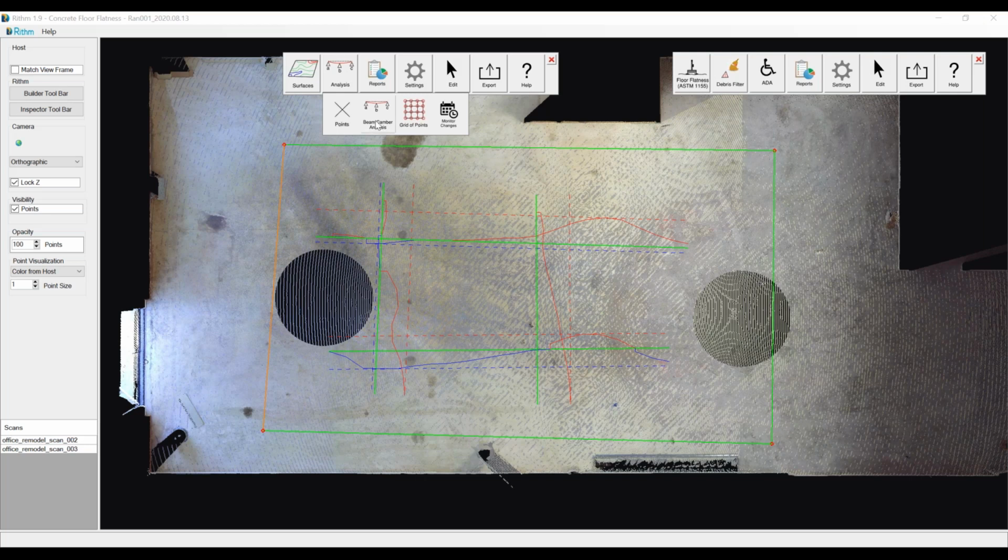We can also do this with a beam camber analysis. So if you're pouring an elevated concrete deck that's held up by steel joists, you can scan the deck from the underside and measure the beam camber on each of the steel beams. And then using the monitor changes, we can look at the change in camber pre and post pour.